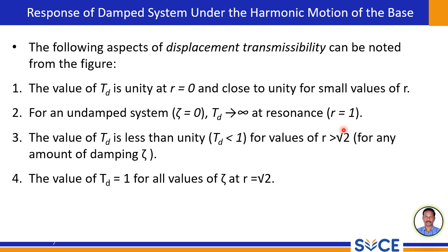When the excitation frequency matches the natural frequency, we get resonance. The amplitude of the mass vibration theoretically becomes infinitely large. Of course, in real world scenarios, there is always some damping which limits the amplitude, but the principle of resonance remains important.